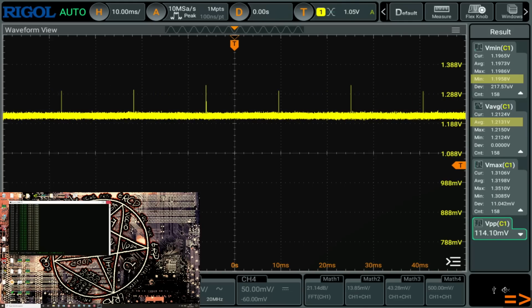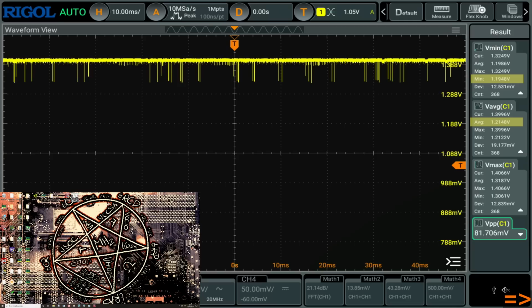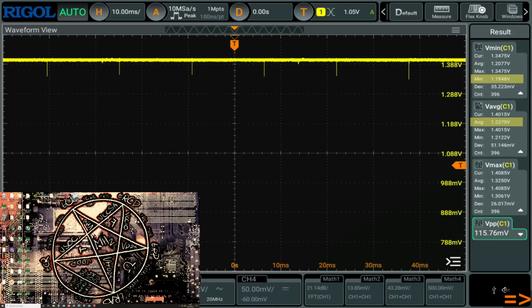So yeah, pretty interesting feature that MSI has here. It basically means you can use mode 8 LLC and just use the load line saturation to tune out most of the excessive idle V-droop. Still doesn't justify having 5 redundant LLC settings, but this is a pretty neat feature.